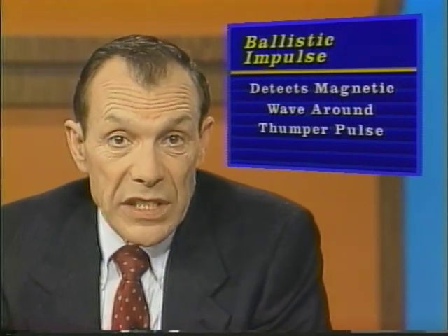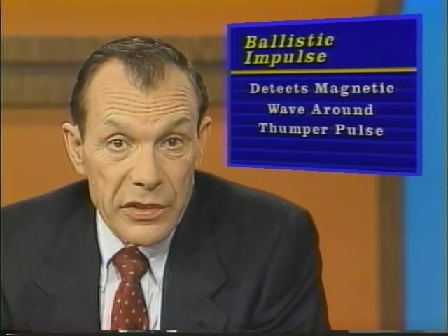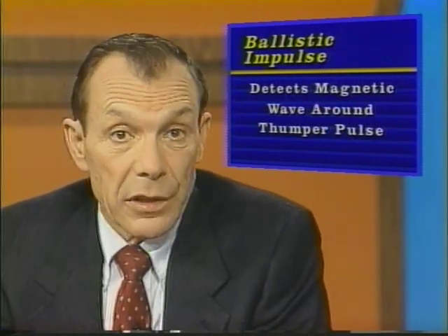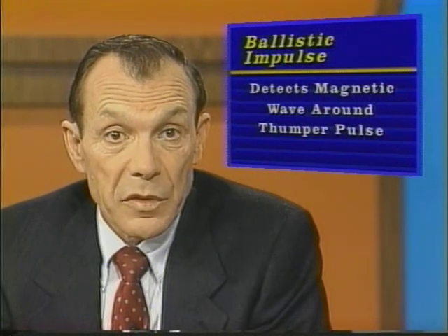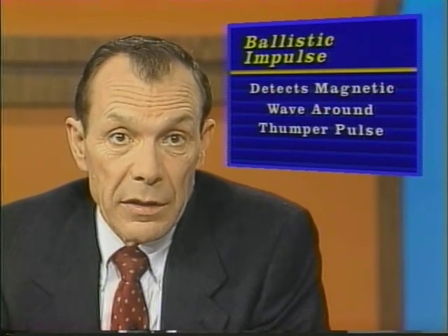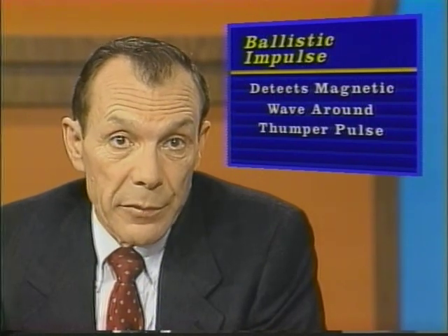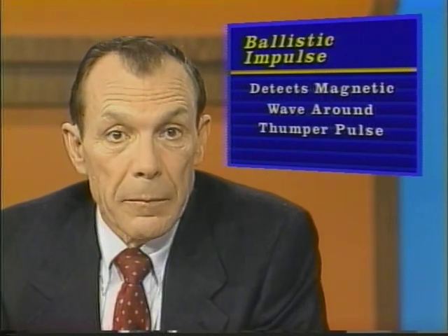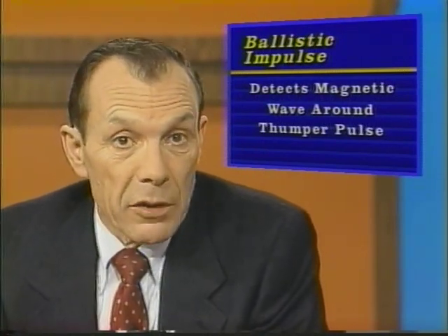The way to hold the receiving antenna to see the pulse is different with each instrument, so read the instruction manual and learn as much about your instrument as you can. You should be holding the antenna over the route of the cable. Using the receiving antenna, it's nothing more than a cable locator. The nulls and the peaks found by the way you hold the receiving antenna on the cable locator with respect to a cable route will also apply to how you hold your ballistic impulse detection instrument.